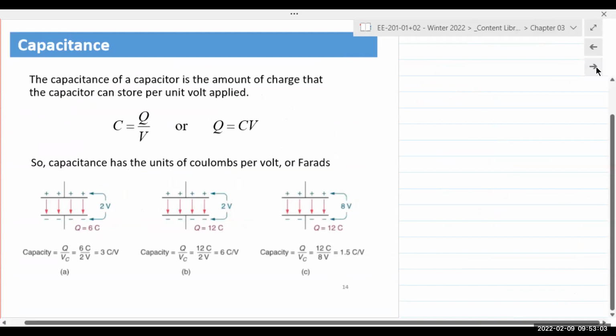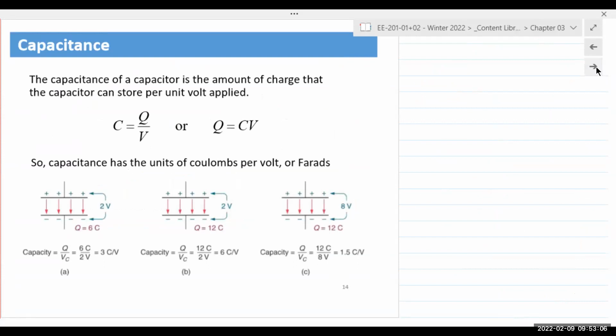All right, so capacitance of a capacitor is simply defined as the amount of charge it can store for every unit of voltage that is applied. So C is equal to Q over V, right? Capacity to store charge, Q, for every unit of voltage that you apply. So Q, the total charge stored in that capacitor, is given by CV. And then I, current, is the rate of flow of charge. So dQ over dt gives us C dV over dt. So I is C dV over dt. We'll see that in the next slide. But that's where it comes from.